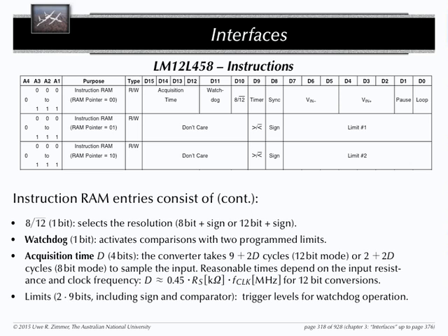And most computer scientists have the concept that watchdogs often have a relation to time, that you set a watchdog timer. This is not a watchdog timer. This is a watchdog value limiter. And often, if you want to monitor, for example, a certain temperature, it's nice to actually measure this temperature and to plot something on your little device, how the temperature progresses at the moment. But often you actually don't care about the value of the temperature. The only thing you actually care about is if this temperature goes outside my limits, please press the big alarm button. It's the only thing you're interested in.